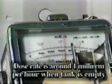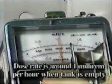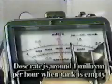Sources are chosen so that the dose rate at the detector is only around 1 millirem per hour when the process material is absent or the tank is empty. These sources are typically 100 to 1,000 times weaker than those used by radiographers to check pipe and weld integrity. Once the source strength has been determined, the expected radiation levels and projected worker doses can be easily calculated.